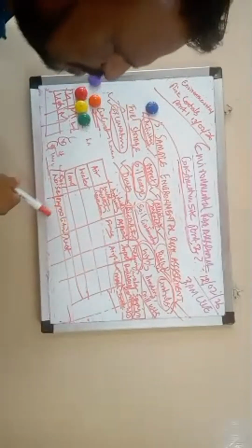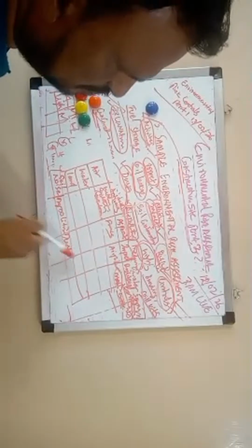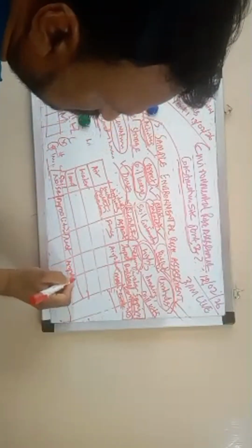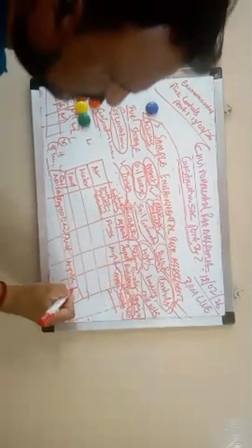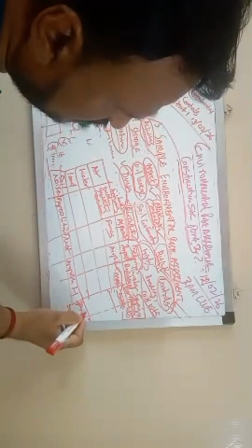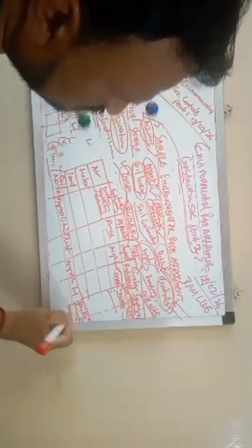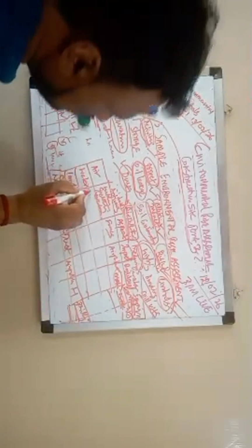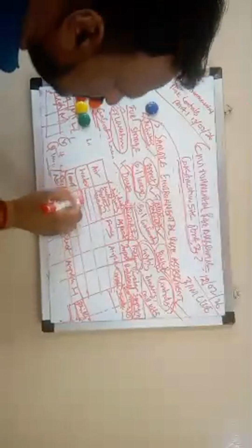So, during demolition, dust will be generated. Then here again there is air pollution. What will the risk level be? High, because a lot of dust will come. Control measures: spraying water and a barricade. The same applies for the concrete work, painting work, or cleaning work.